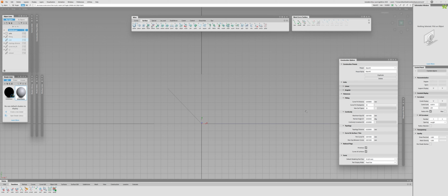So the first one is fitting. And this is the most interesting one, and it actually has a really huge impact on everything else. Now, before we talk about this, I would like to mention that in most cases, the engineering department or your client and client's engineering department, if you're working as a contractor or freelancer, will not give you any of those except the continuity. So the continuity are the main ones, and everything else is designed to help you build to these continuities. So you rarely see the fitting values in the technical documentation. Well, sometimes you can, but that's a rarity. I would say the rational flag is sometimes specified, but we will talk about that a little bit later.